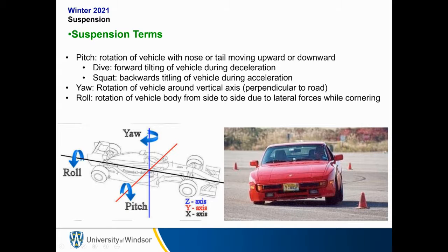If you have a very powerful car, such as one on a drag strip, you can actually lift the front end in the air. Now, that's not really to do with anything in terms of the aerodynamics of the vehicle or weight transfer. That's more to do with the drive shaft riding up on the differential, but that's something else. So we have dive when you decelerate hard, or squat when you accelerate hard. Vehicles can't necessarily always squat if they don't have enough power.